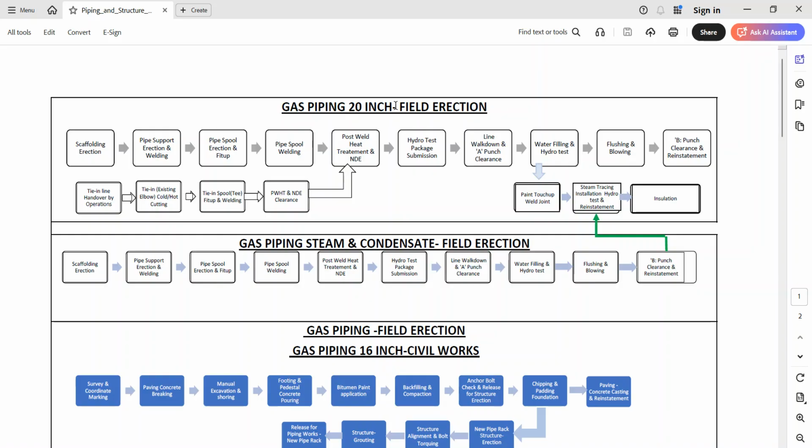For that you may need some duration. Getting the films also takes some duration. If you do the radiography at night, you will get the result by next day. Then you check the film, whether the metal is poured uniformly or you have some porosity or defects. For this also you need some duration.